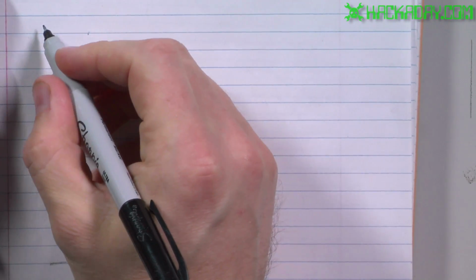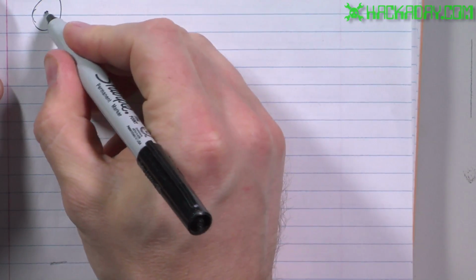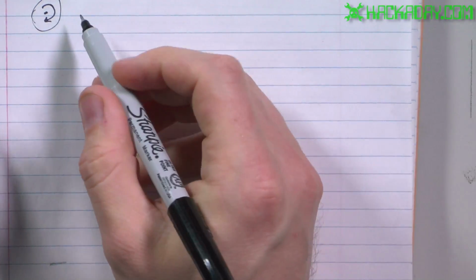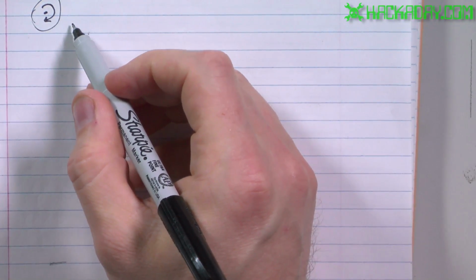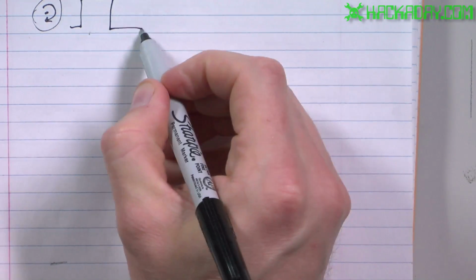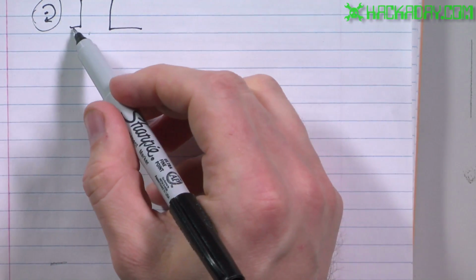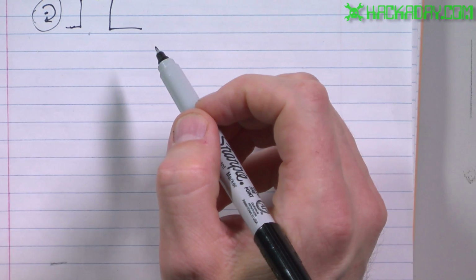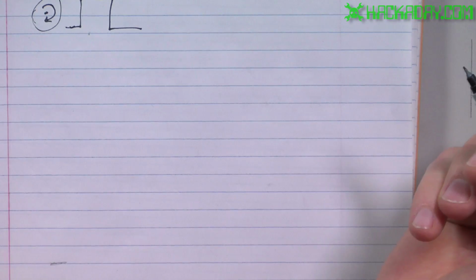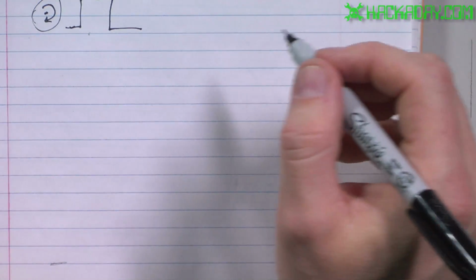Let's say we have a motor or something that we want to turn at a certain speed. Now, with a digital device, we have full on or off, and those are our only choices. So if we have that connected, say with a MOSFET to the lead of a motor, it can be either full on or full off, unless we do something called pulse width modulation.